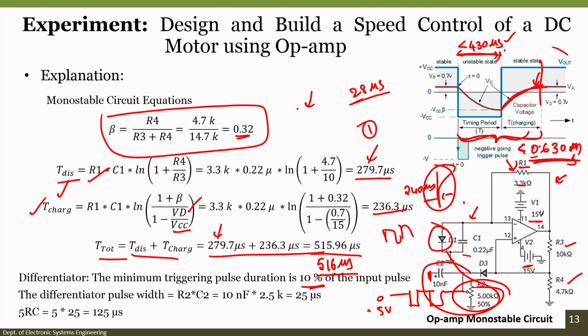In order to get this negative spike, the triggering input provided should always be 0 to minus 5 volts, otherwise all the spikes will be greater than that. For that intention we reversed the output of the encoder. Instead of measuring with respect to the ground, we measured everything with respect to 5 volts, so that the output will be 0 to minus 5 volts. I hope this is clear now.